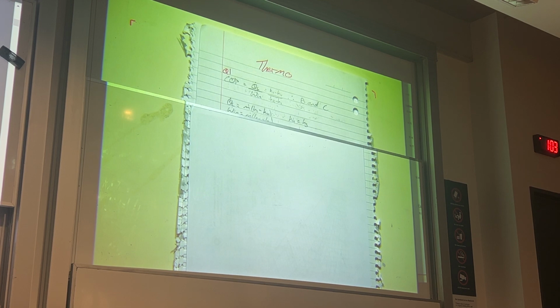Question 2 is based on psychrometry. So here we've got a bit of understanding about psychrometry, and we want to design an air conditioning system for our house. So our room conditions are dry bulb temp of 29 degrees Celsius at a relative humidity of 40%. We aim to remove around 14 kilojoules per kilogram of heat from the air at constant relative humidity. So we've got a few statements to select from.